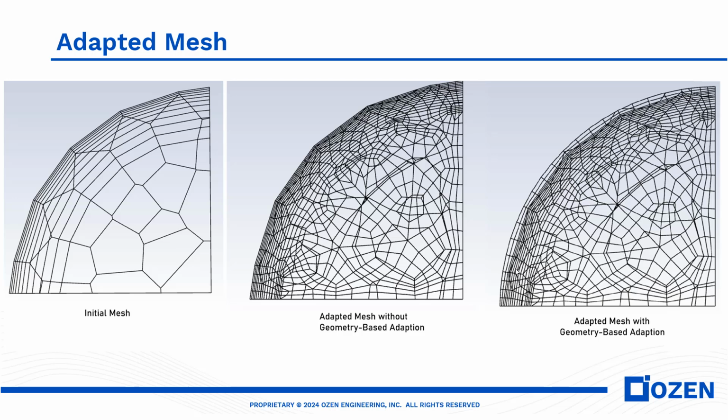One more thing: if we want to work with manual refinement for complicated geometry, in this example it is a very simple geometry, but in industrial applications the geometries are not so simple. We need real time and effort to get a good quality mesh after manual refinement. It is doable, but costs time and effort, and does not necessarily mean we have a good mesh.